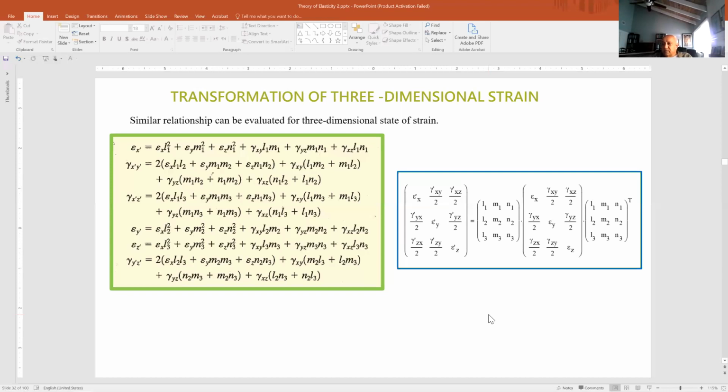So basically every quantity in physics would be explained in terms of tensors of the 0, first, second, or higher degrees. All of them behave the same way. Every property we mentioned here would also be applicable with, for example, moments of inertia. There are 3 mutually perpendicular directions about which moments of inertia are either maximum or minimum, and the products of inertia are 0.